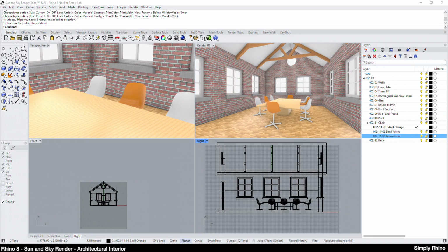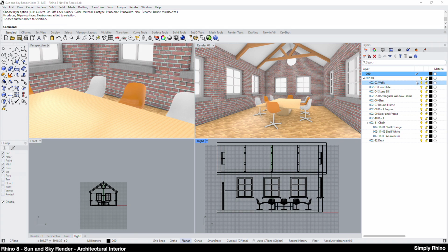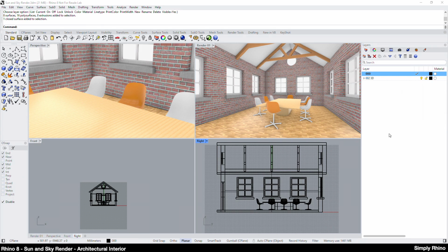Now I've added some basic materials, the next thing I want to do is to look at the lighting. At the moment, Rhino is using its default lighting system, which is essentially that of a photographic studio. This is a good starting setup for product design scenes, for example, and is set up with a grayscale 360-degree environment created from an HDR image. This studio environment is used both to light the scene and create the reflections, whilst the white background is controlled separately.